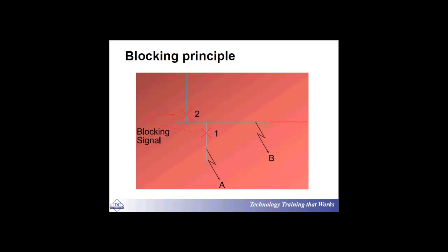Sometimes, again, by means of that communication, you are, for example, applying intertripping techniques, so that as soon as one relay operates, a signal is sent to other places, saying, hey mate, I would like you to operate as well at the same time.